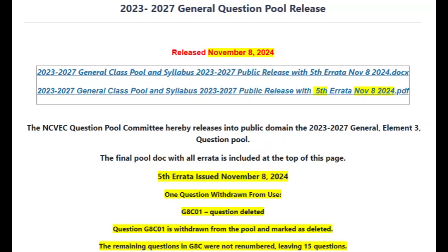G7C10B. What is an advantage of using IQ modulation with software-defined radios, SDRs? A. The need for high-resolution analog-to-digital converters is eliminated. B. All types of modulation can be created with appropriate processing. C. Minimum detectable signal level is reduced. D. Automatic conversion of the signal from digital to analog.